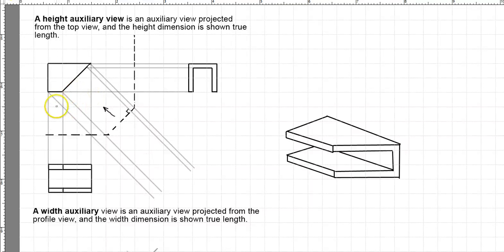Once we are done with that, we are going to be measuring the distances from our folding line. So if we look over here, we are going to be measuring from the folding line till this distance right here, which we are going to call x. Then we will transfer the same thing onto this side, x.